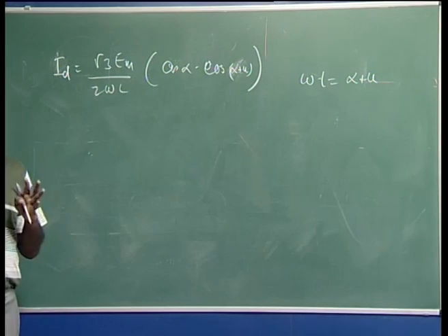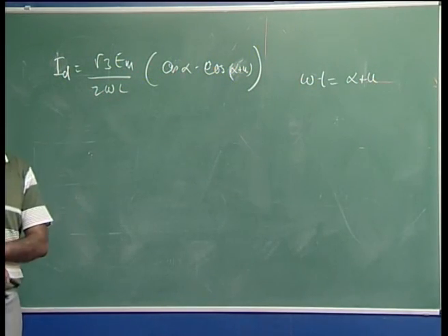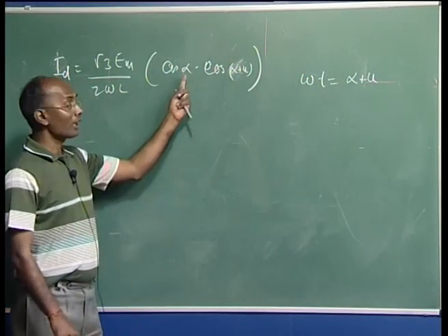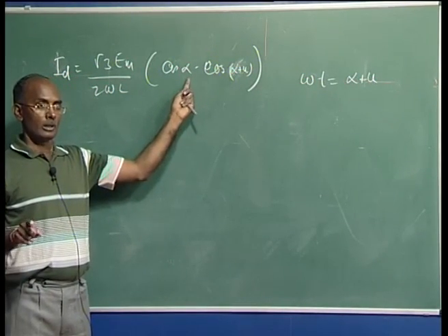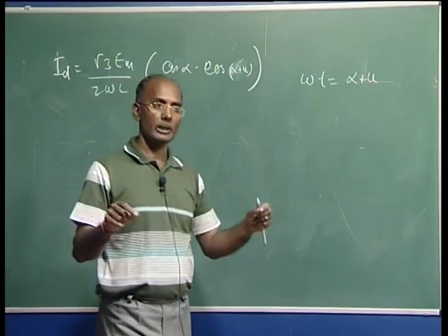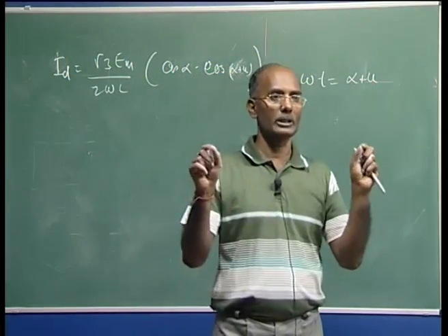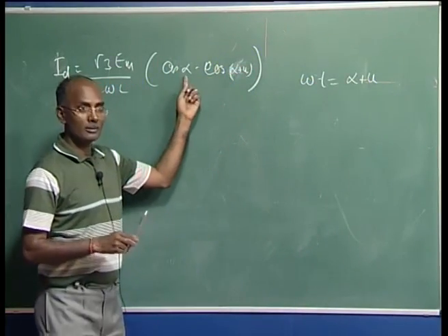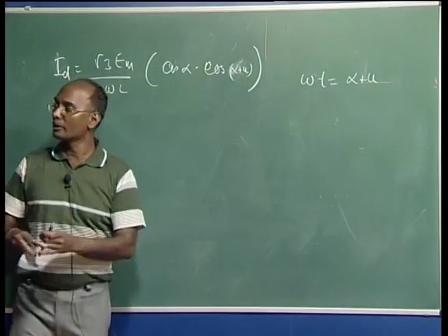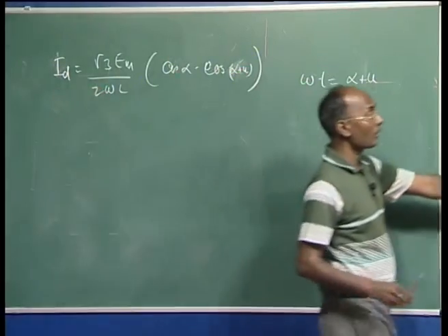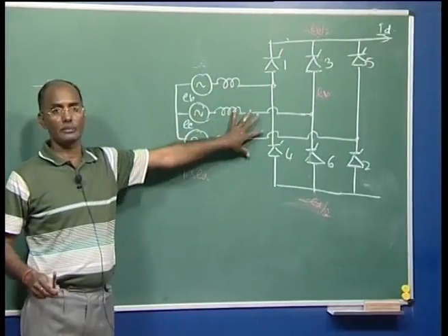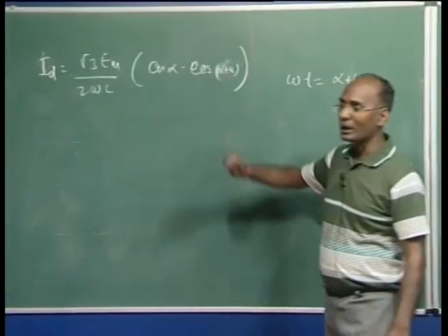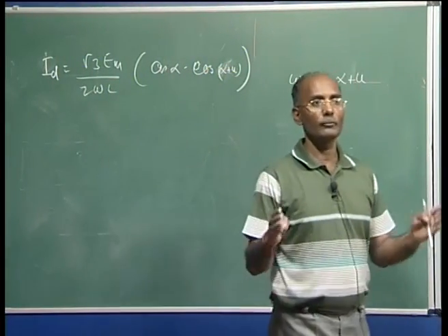Why do I want to express this in an electrical circuit? Because the measurement of u is very, very difficult. This alpha is in your control. The current in the limb is in your control, because some controllers are taking care of maintaining the current. So, the DC current is controlled, your alpha is controlled, but this u depends upon the different circuit parameters here, what will be the L, what will be the source here, and this depends upon those. So, that is not in your control. So, I want to eliminate this u altogether, and we can write the expression in terms of V and Vd.